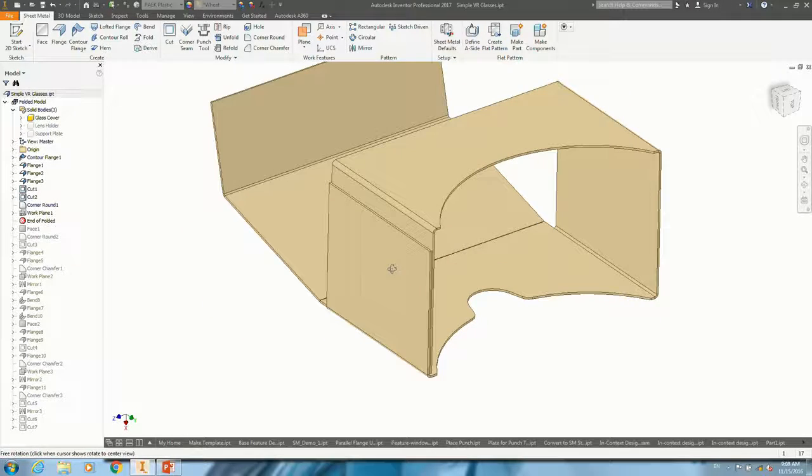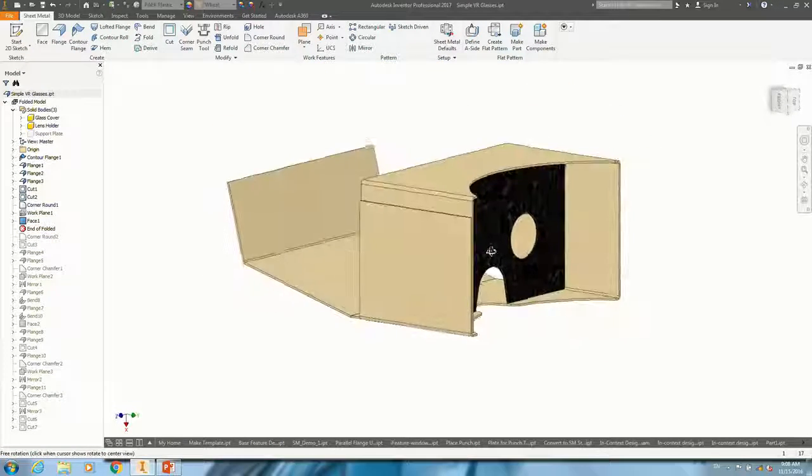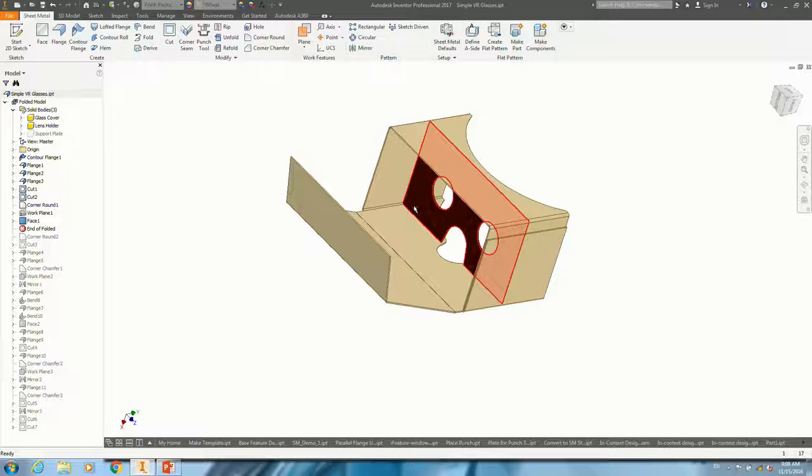First, I create this cover body with some geometry information. And then we go to create this face. Since there is a fixed distance required from the end face of this cover to this face, we just reference this face to create a work plane to place the second solid.